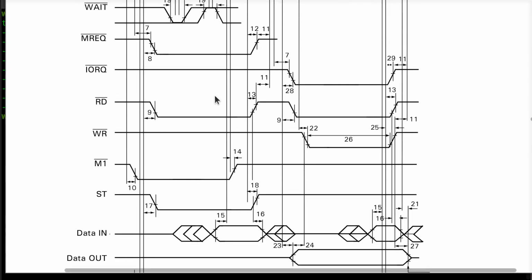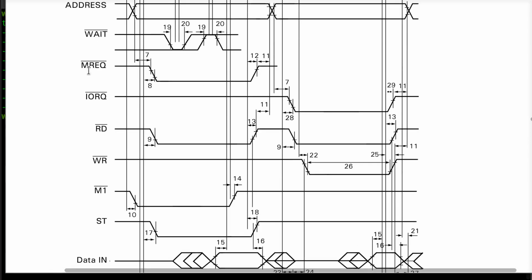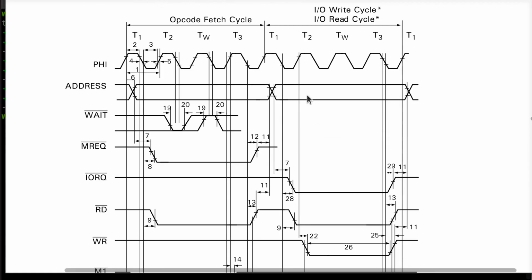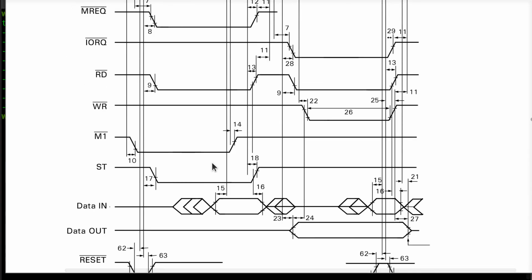Now down here it shows you the relationship between the falling edge and the leading edge of these memory bus and the I/O bus request boundaries here. The tenure of this bus transaction. And much like the address bus, up here it says the address will be valid before the I/O goes valid, and it'll stay for a hold time afterwards, and so on. Just like it does for a memory transaction.